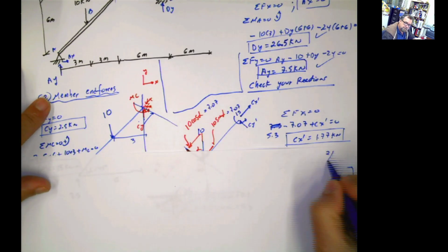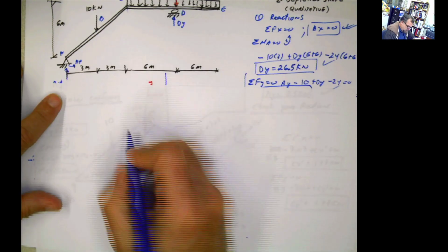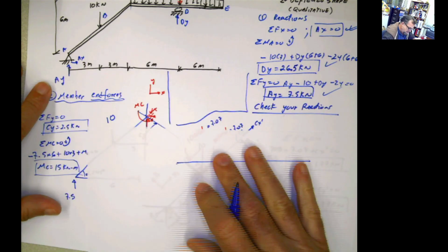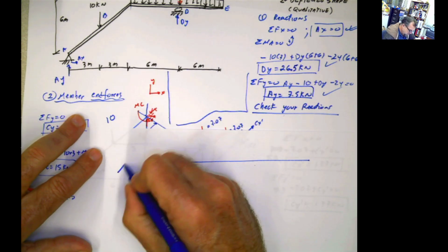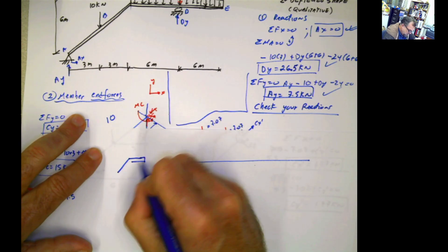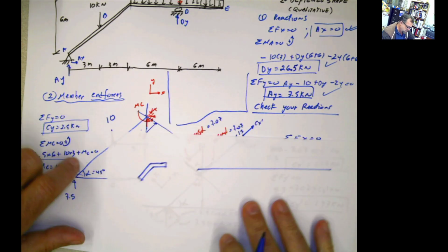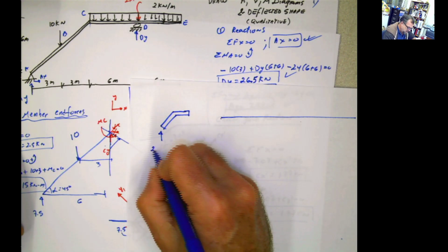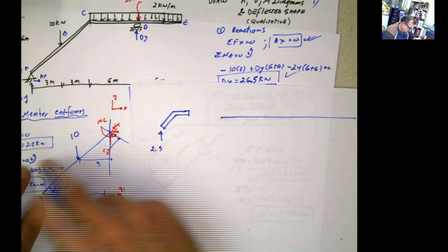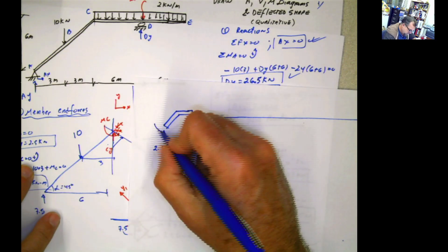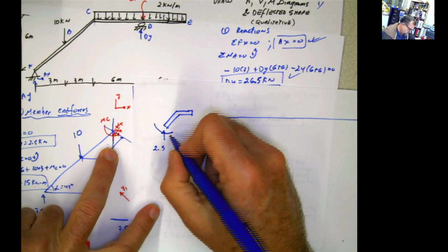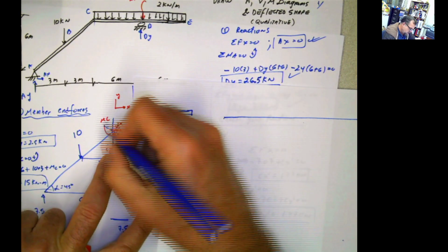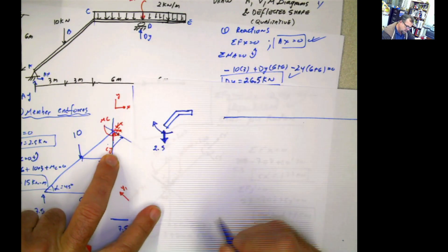2. I'm gonna put that member and only that member over there. So here. Should I study the joint? Well, we certainly can study the joint if we want to. This is what we have. But using this part, I calculated this value CY, and CY was 2.5, and the moment that we calculated here was acting in this way. So in this case, meaning if it was acting up, here it's going to be acting down. If it was acting in this direction, now it's going to be acting in that direction.